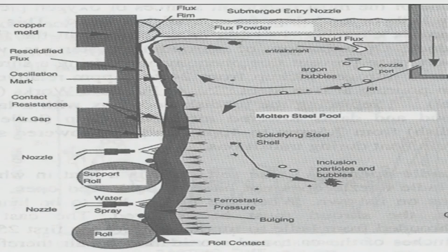Now, after the tundish, when you are using continuous casting, there is a continuous casting mold, whether you are casting bloom or billet or slab, whatever it is. The shape of the mold of course is different depending on what you are casting, but there has to be a mold. What is a mold? Unlike ingot casting, it is an open mold. You see, this is the mold surface, this is made of copper, this is a water cooled copper mold.